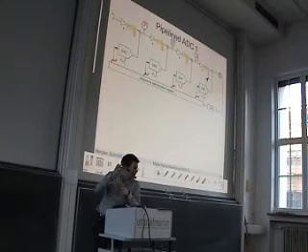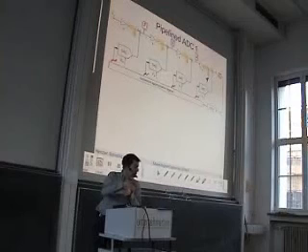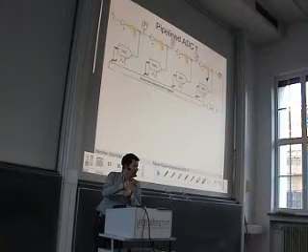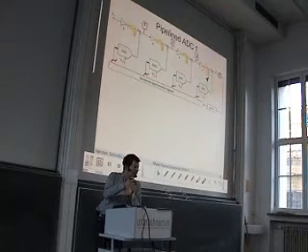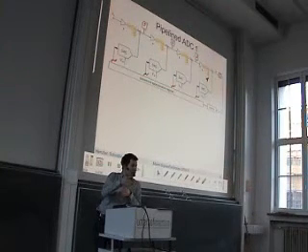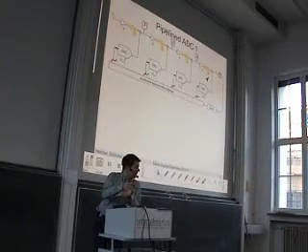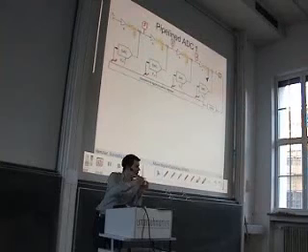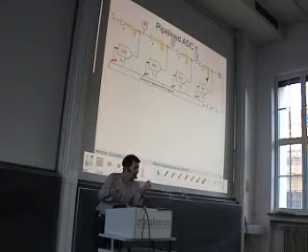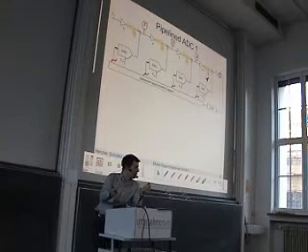This means after each iteration clock, new data is available. This means we have increased the throughput by a factor of n, because data arrives each cycle and not 1 out of n cycles. However, it still takes the same time until the data at the input arrives at the output.